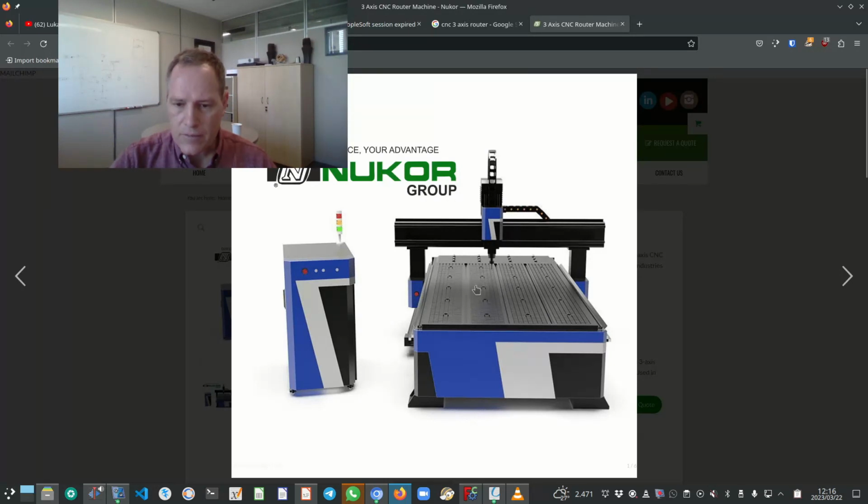Okay, so we need to dimension the side plate right such that we control the distance, the depths from the one side, not from the other side or from both sides. That's actually the important thing. You cannot dimension depths from both sides of the plate. You can only dimension a depth from one side of the plate. Okay, and that's because of the way that it will be manufactured.